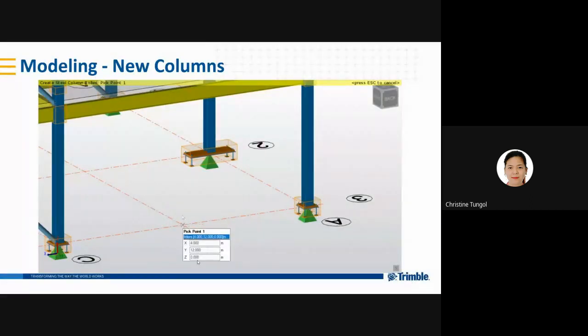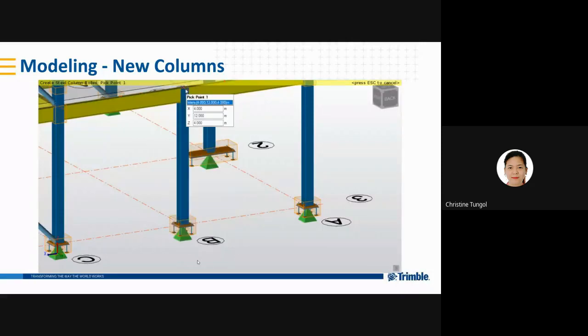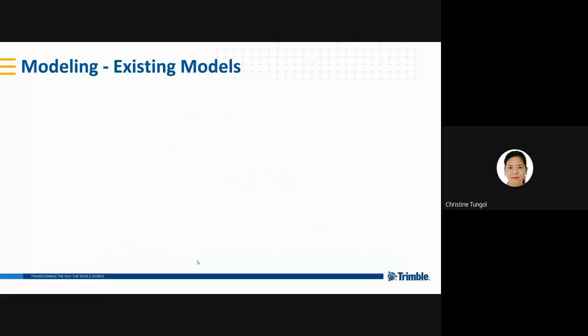So base plates are automatically added on creation of a steel column, just like a support. Regardless of the foundation type, base plates are automatically added to the bottom of new steel columns if a support is required or applied. A base plate will not automatically be added when the column is supported by other members, slabs, and walls. There are two situations to consider.